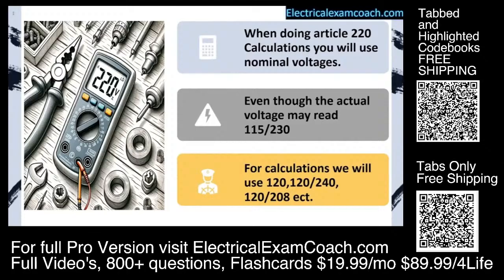When doing Article 220 load calculations, we're going to be using nominal voltages. Although our actual meter reading might be 115 or 130, for our calculations, we're going to be using nominal system voltages like 120, 120/240, 120/208. It makes it a lot easier to do these calculations, not having to guess or wonder what the actual voltage readings might be.